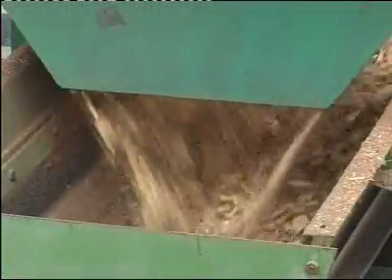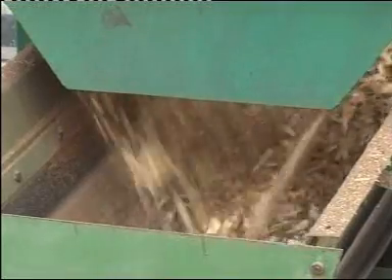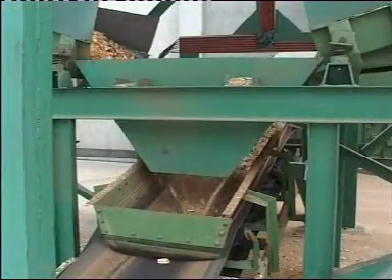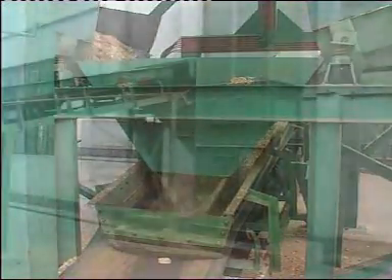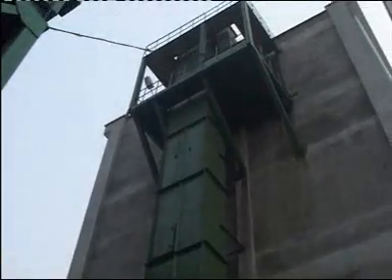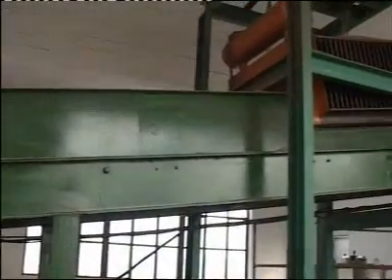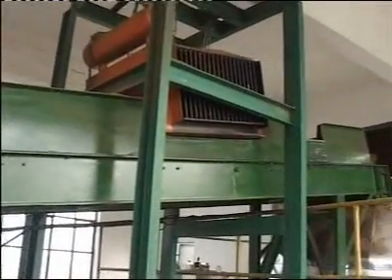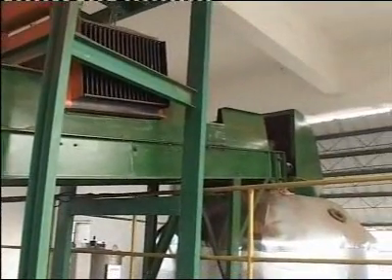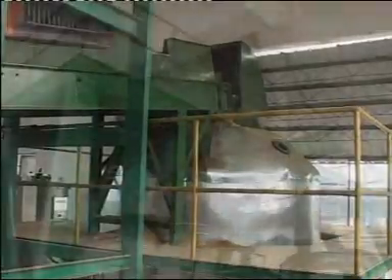Wooden chips are transferred to the belt conveyor by oscillating outfeeding chute, which locates at the bottom of chip silo. Transferred by belt conveyor, wood chips are lifted by bucket elevator to the higher position. Via belt conveyor with metal detector, the chips are fed into the pre-steaming bin, in which the chips are pre-softened by hot steam.